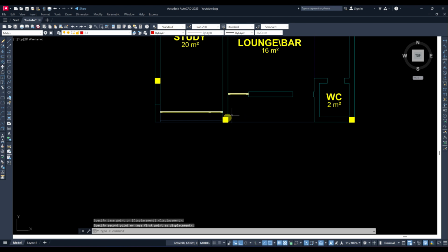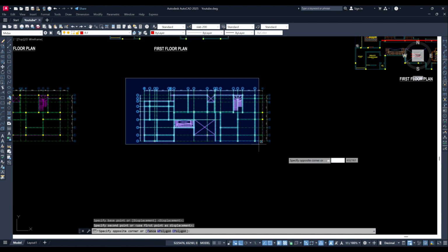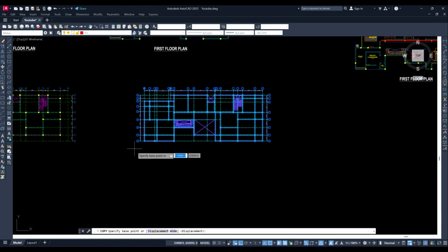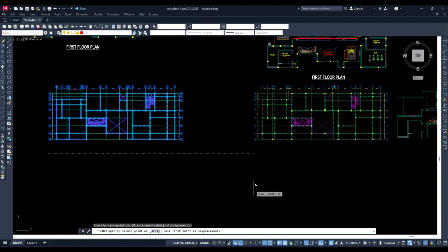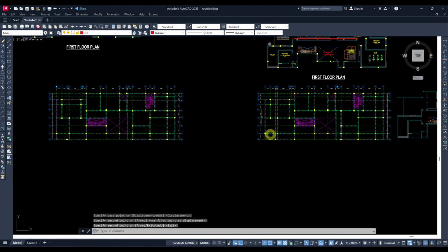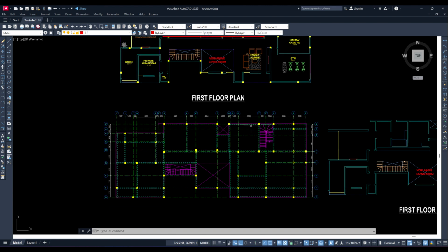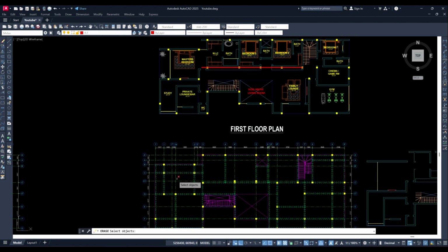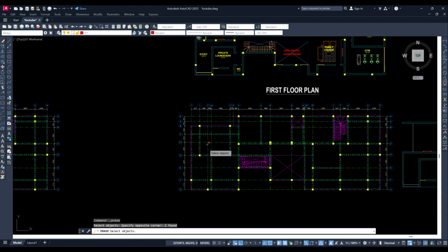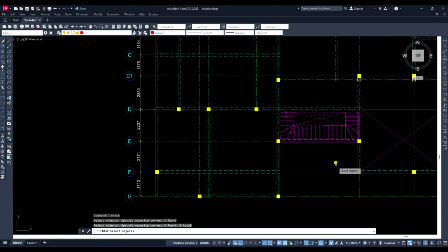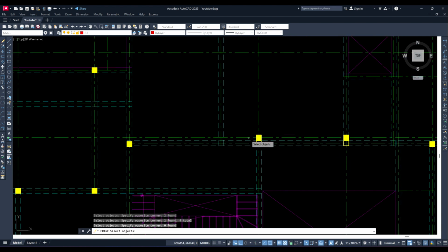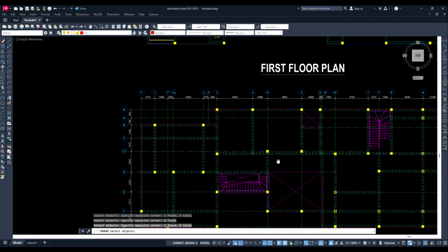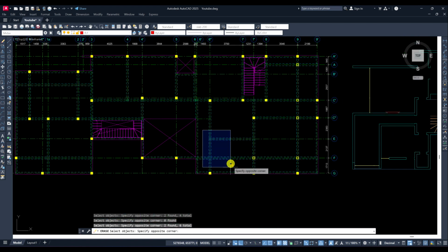So that was the column I moved to the other end, so it flushes with that block wall. Since I just made that correction, I have to delete that and copy this modified first floor layout. So now, since the terminated columns, we are not going to see them. Since they are terminated, we have no business with them on this roof level. So I'm removing them now.